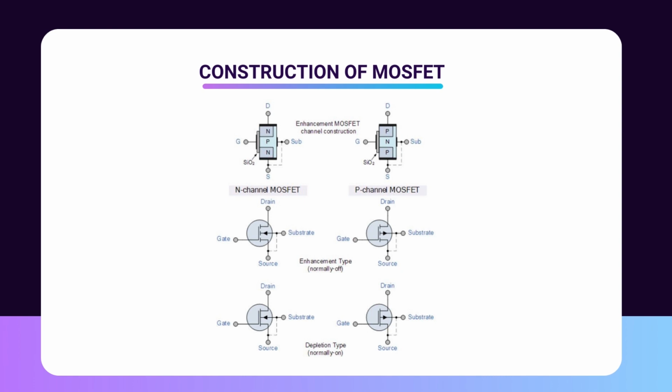So, this was about the construction of a metal oxide field effect transistor. Now, all the FETs, field effect transistors, whether it be MOSFET or JFET, have first of all high input impedance, and second, they are excellent for switching ability. Why are they excellent in the case of switching ability? Because they are unipolar devices. There is no role of generation and recombination present here. Current flow is only because of the majority carriers. There is no role of minority carriers present in such devices.